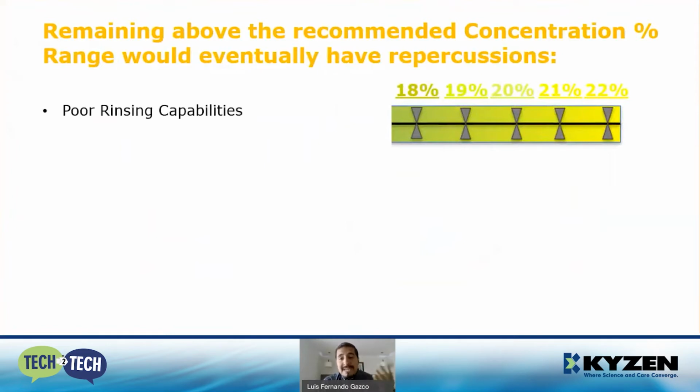Poor rinsing. The higher the concentration, the higher the rinsing needed to achieve the expected results. Your rinsing could no longer be enough to finish removing all chemical and flux residues. A high concentration also could cause material compatibility issues on sensitive metals. Some chemistries contain inhibitors to protect these materials, but when used at higher concentrations, the product could become more aggressive and attack them.